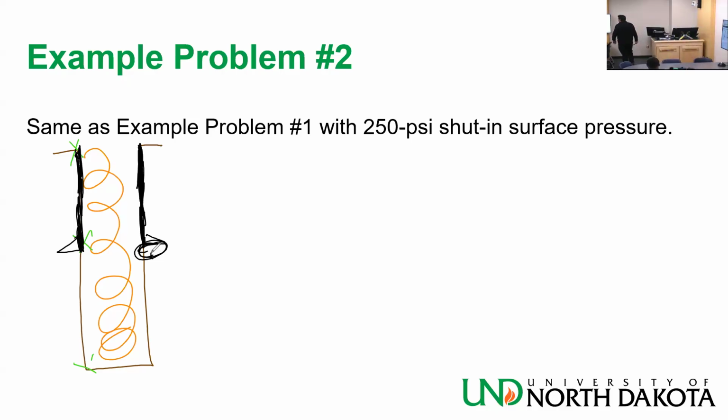But yeah, that's why, when I'm running casing and anything I do to the well, if I'm worried about fracturing, I'm worried about fracturing at that casing shoe, what Coyote said, at the casing shoe. Okay, this is my most vulnerable point. So I want to run casing as deep as I can, right? You know why now. I want to protect as much of my well as I can.